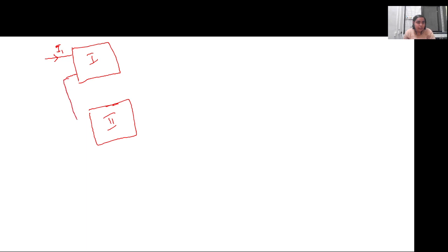So whatever the current is here is also flowing in here, right? Yes, ma'am. So I2 current is flowing in and I2 current is flowing out. The same current is going to the second network with I2. Only the voltage will be added. So if this is V1 dash, this is V1 double dash, this V1 will be the summation of these two voltages.